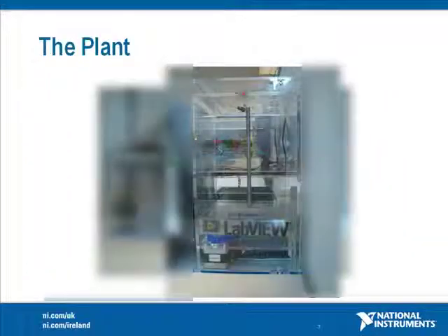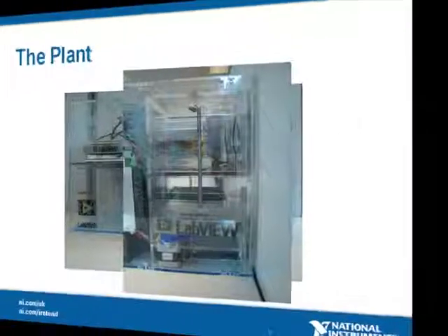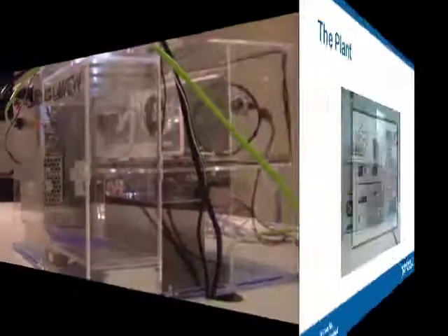In the lift section of the plant we utilized the FPGA with a single C-series digital module. This digital module was used to send commands to the stepper motor drive, telling the stepper motor drive which direction and which speed to travel in. We also closed the loop using limit switches, so we knew which position the lift was in.